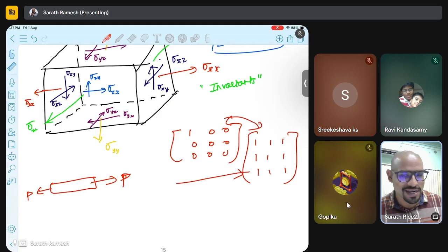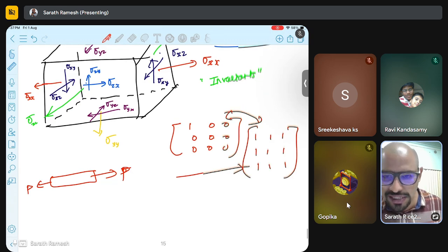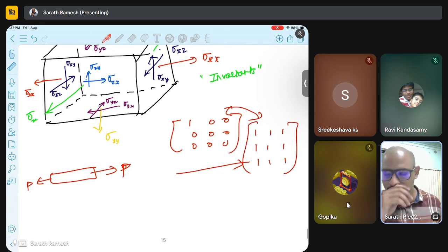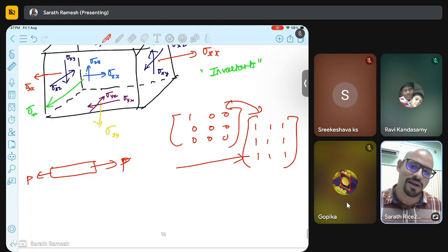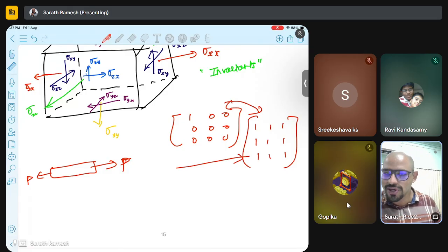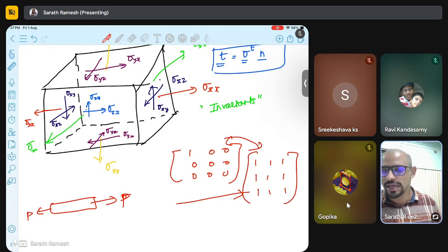This is a uniaxial state of stress. This is something like xx, yy, everything is there. So how can it be uniaxial? But it's a tensor. When we compute the invariants of it, they will be the same. So what are these invariants? We'll see in the next upcoming week's course. There are three invariants. The trace of a tensor is the first invariant, and we have second and third formulas, right? We can calculate them, and they won't change if we change the basis x, y, z.